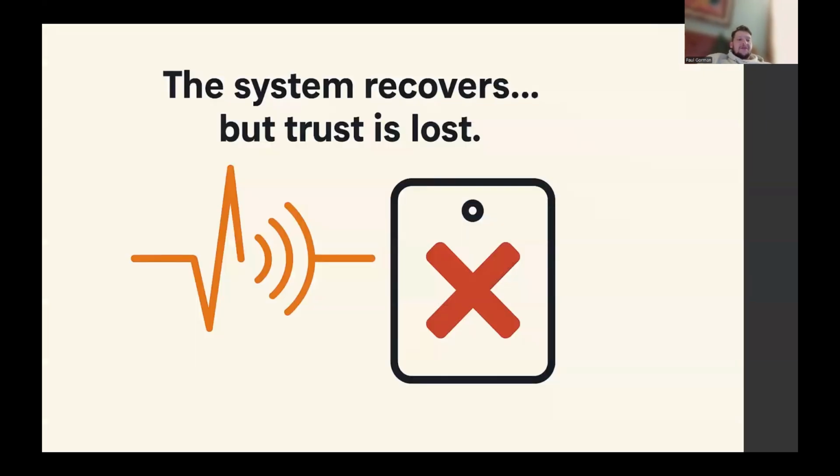So, even outside of medicine, we see similar consequences in automotive electronics, where an improperly routed ignition or injector line can radiate enough noise to reset the ECU and leave you stranded on the side of the road. Or maybe your Nintendo Switch controller just breaks down in the middle of a battle. So, while the failures may not always be catastrophic, the cost of poor electromagnetic design includes system instability and unpredictable behavior, all of which are avoidable by applying these ECE 303 logic tests. In other words,